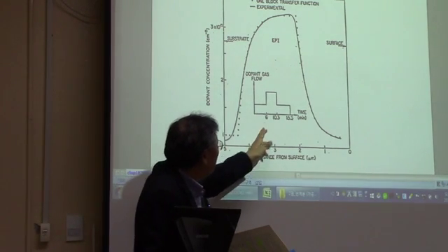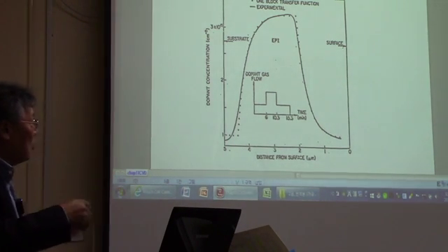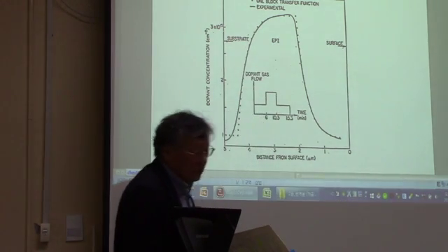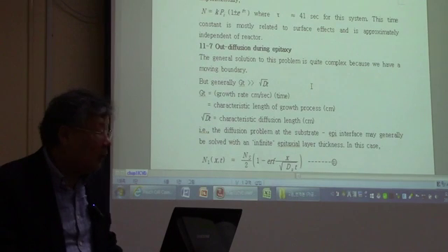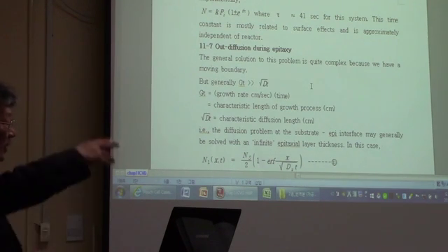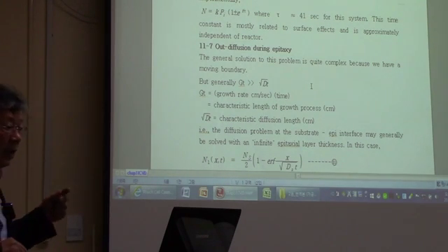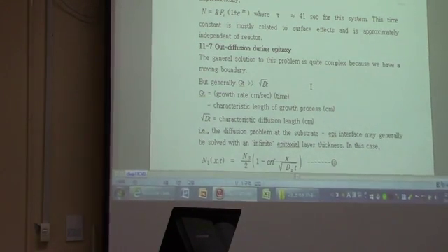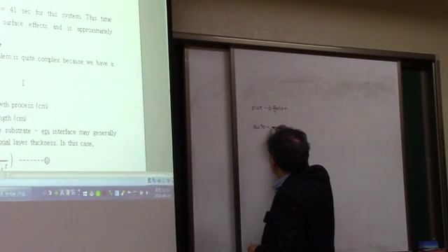See, of course, even though the gas has been switched on and off like this, the dopant concentration incorporated into the epitaxial layer is not these right angles. You can see the slow curves in the dopant concentration. And that is what we call the dopant concentration profile, which has to deviate from the ideal curves that we expect because of two facts. One is the out diffusion of the dopant, and the other thing is the auto doping. Okay. Out diffusion and auto doping.